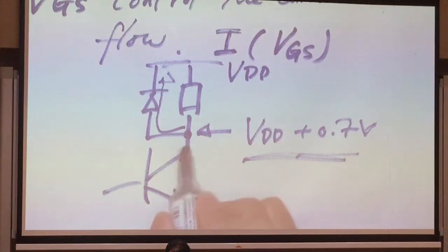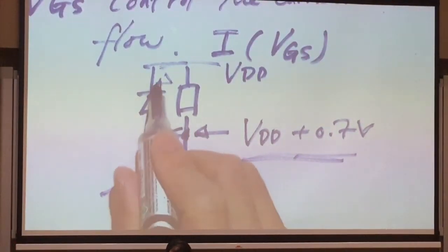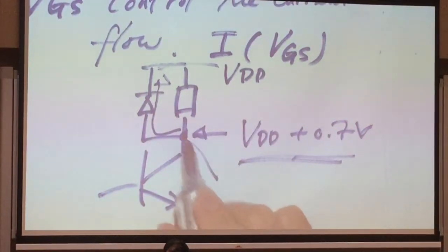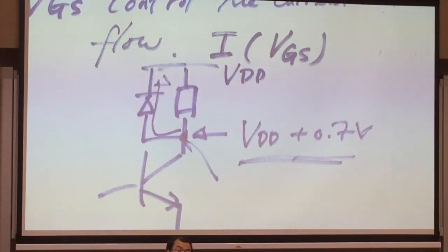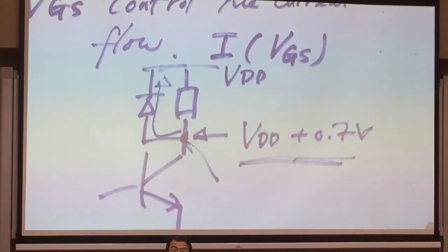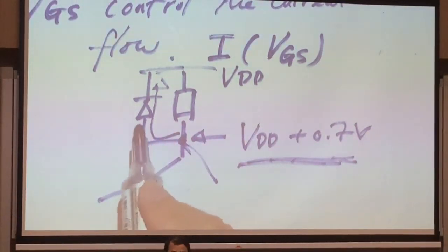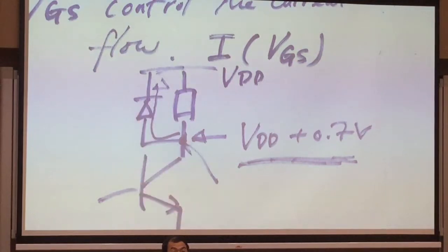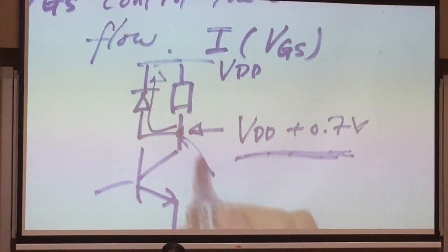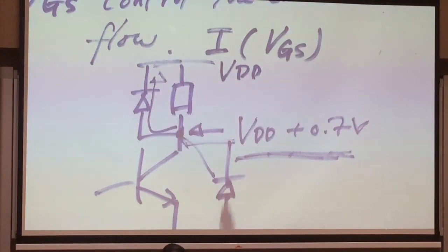Great. So in this way, you can protect your device. If you don't have these diodes, this voltage here can be higher because of the inductive action here. So this one you will see very common. Why do you need a diode here? Usually it's for protection purpose. And sometimes you will see an additional diode from here to ground.